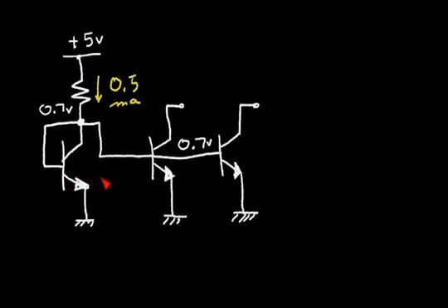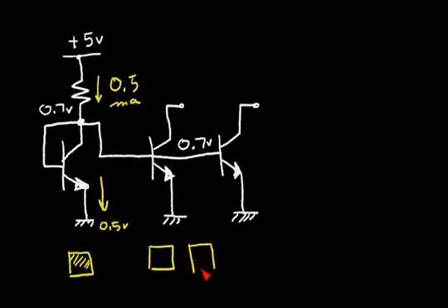Let's say that I have this half milliamp flowing in this emitter, but I'm going to adjust the emitter of this middle NPN to be larger by a factor of 2. So if I draw the actual physical layout of this emitter at the left, it could perhaps look like this, a perfect square, and have a certain area. Now the transistor in the middle, I want to have an emitter with twice the area. So one way is I could lay out 2 identical emitters. So the area of these 2 emitters is twice that of the area of the transistor at the left.